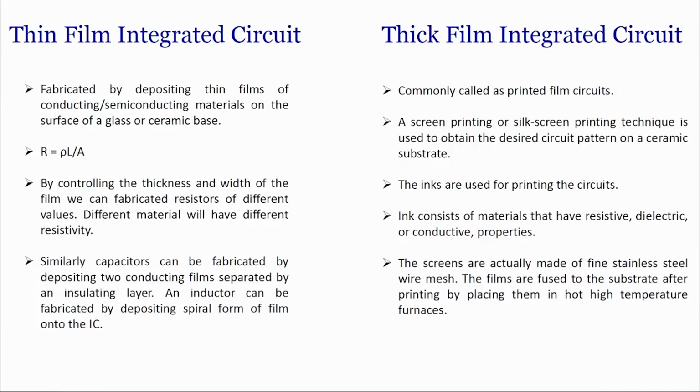In case of thick film technology, it is commonly called printed film circuits, where a screen printing or silk screen printing technique is used to obtain the desired circuit pattern. Now, the inks used for printing the circuit can have resistive, dielectric or conductive properties, right, and the screens are generally made of stainless steel with wire mesh.